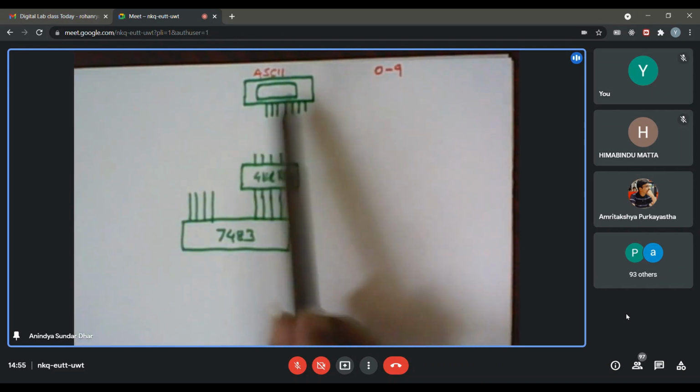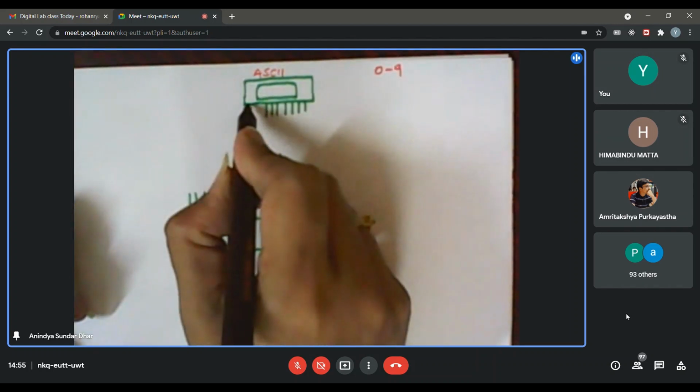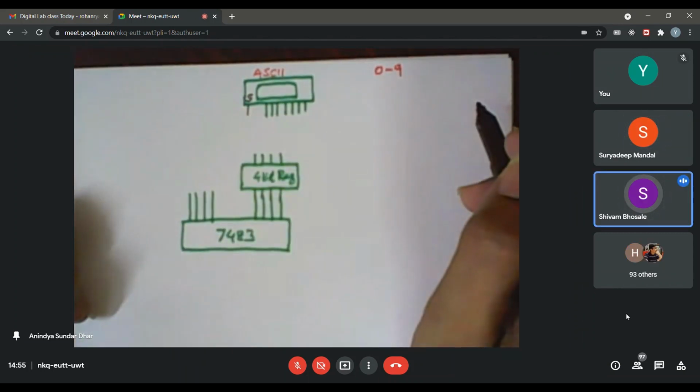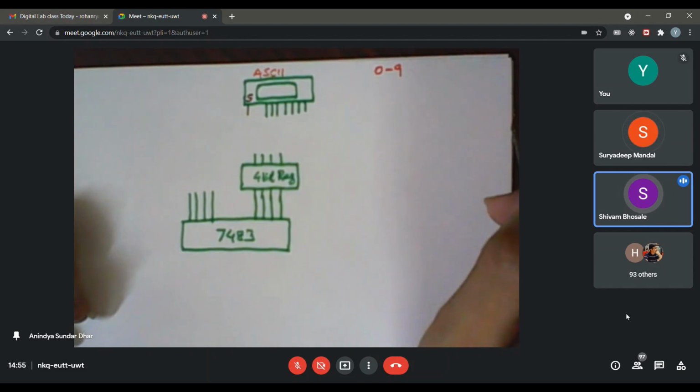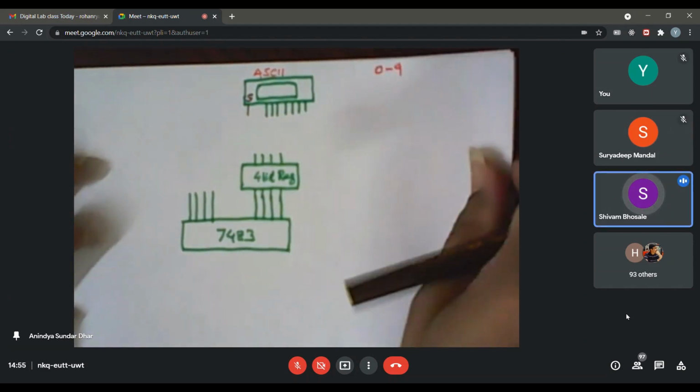So whatever is available, that ASCII keypad 7-bit code with a strobe signal, maybe we can use that. But the LSB 4 bits would be useful if you want 0 to 9, because 0's ASCII value is 48, and the binary is 110000.